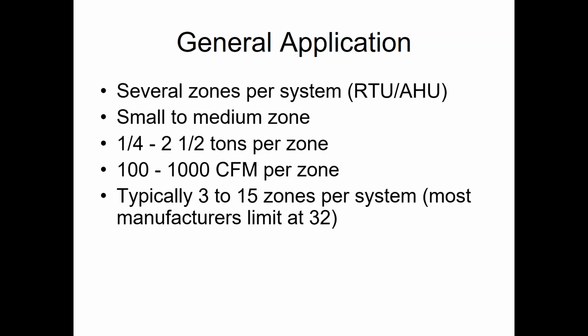You're probably trying to mix an interior zone with a perimeter zone, and that's a huge, massive no-no. Or you're trying to mix the east zones with the west zones, another massive no-no. You can't do that. We'll do some compromises here in a few minutes when we lay a building out, but we can't do anything that extreme. If you mix an interior zone that needs cooling all year long with a perimeter zone that needs heating, I would 100% promise you you're going to have nothing but callbacks. It'll be endless. It'll be brutal. And that's one of the reasons why VVT has gotten a bad rap by some designers over the years. So try to keep that in your head.